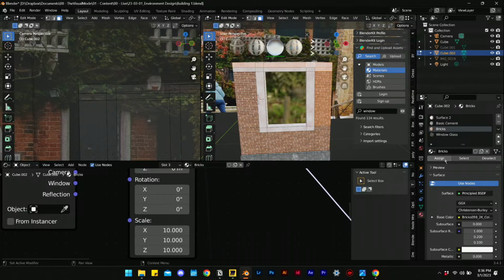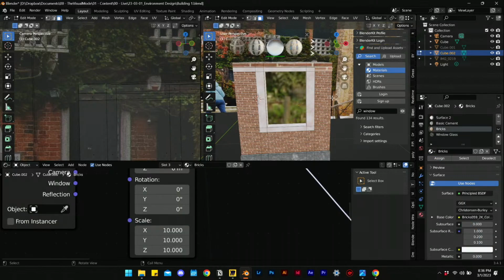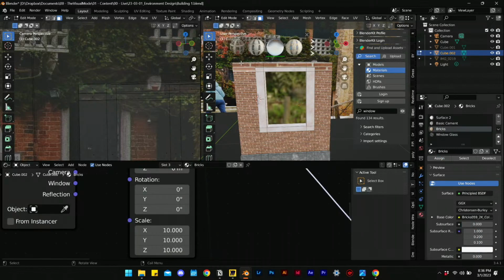So that's the wrong shortcut. I'll just go ahead and assign brick. But what I was saying there is you could actually, in this edit mode, hit Shift G and you can select similar. You can select material and that'll help you just select everything that's the same material at once. So, neat little trick to know.